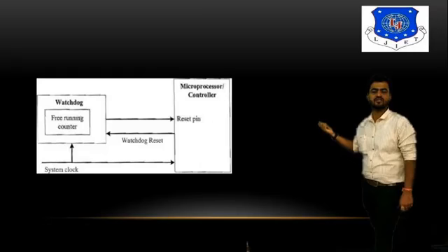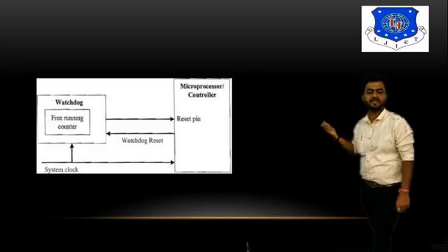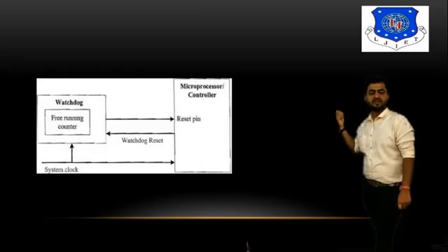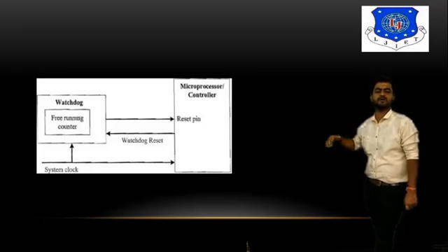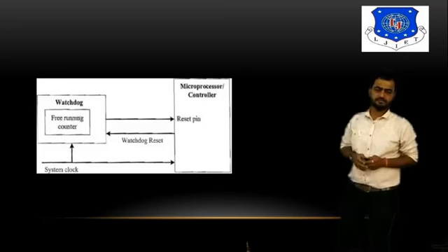So what exactly is the role of the watchdog timer? It will match with a reset pin. If the counter reaches the maximum limit, it will trigger or provide a pulse to the reset pin, and the reset pin resets your whole microcontroller or microprocessor.